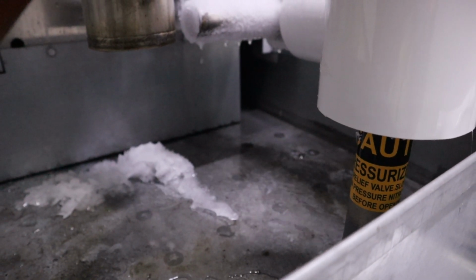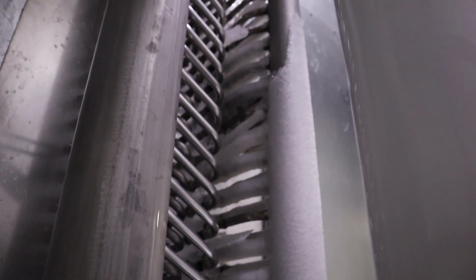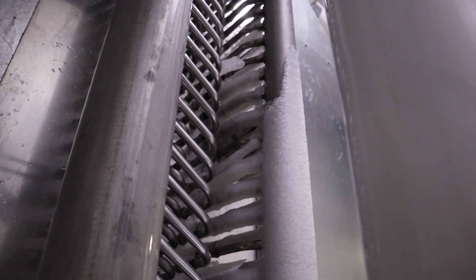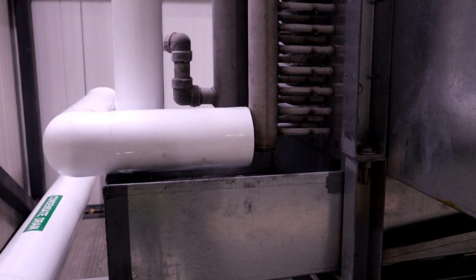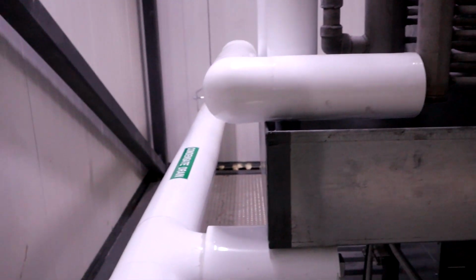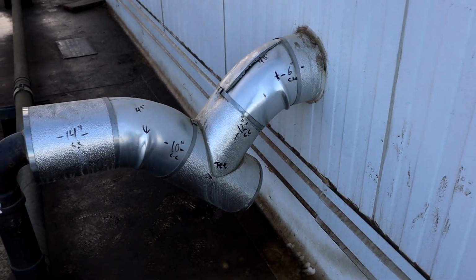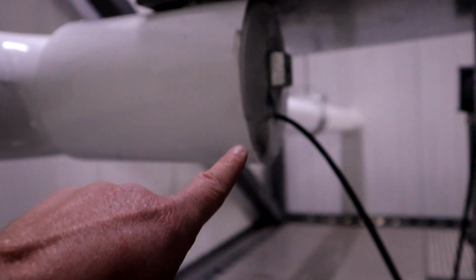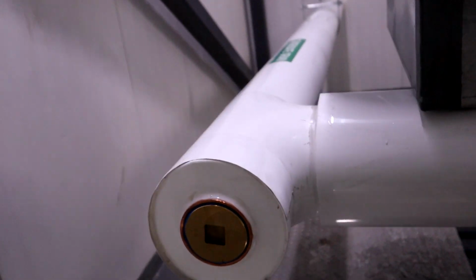When hot gas defrost is employed, the drain pan will typically have tubes piped through it. Warm ammonia vapor will pass through the pan before entering the evaporator. Water that collects in the pan will freely drain through the defrost condensate drain pipe. All drain lines must be trapped. If the room operates below freezing, the drain pipe must have a heat trace to prevent water from freezing in the drain pipe.